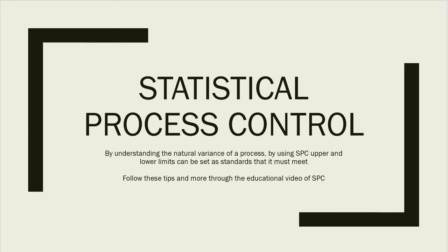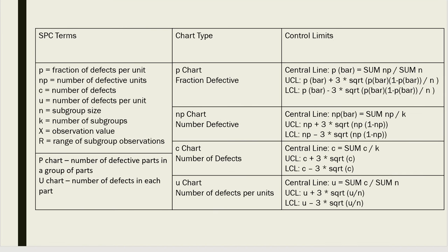To begin, statistical process control is a method used for measuring and controlling the quality of a process or system. This is especially important when it comes to industry situations. More specifically to statistics, SPC primarily relies on the control limits that are established by the capability of the process fulfilling the needed outcome. These control limits are separated into an upper and lower control limit.